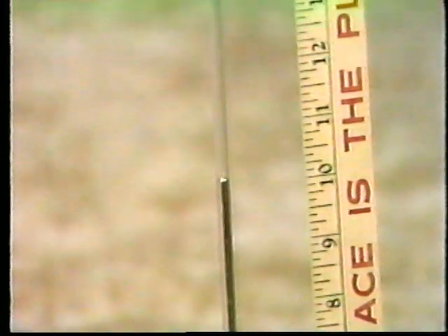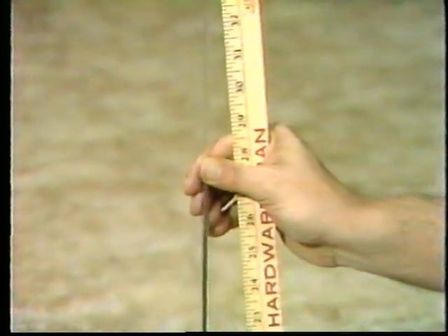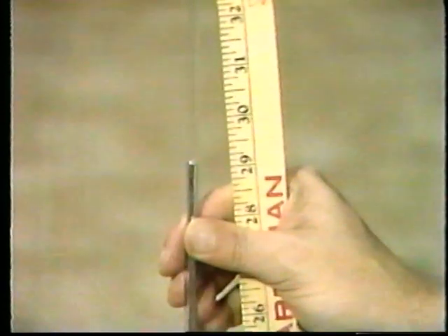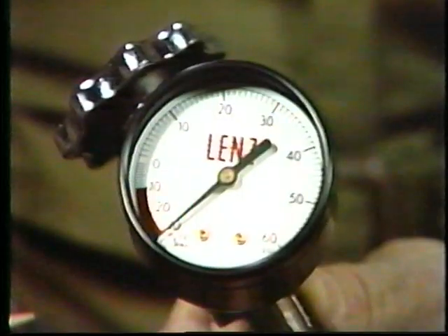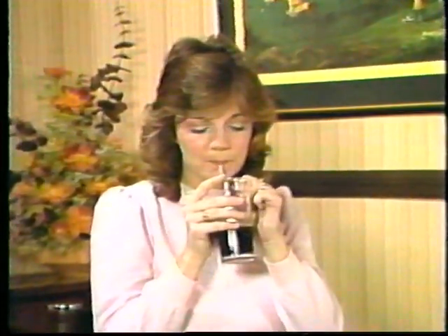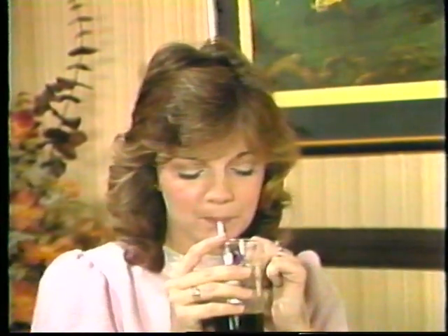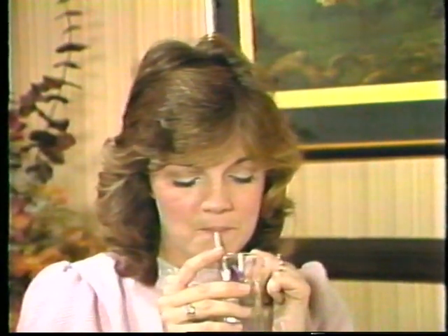If we pump all the air out of the top of the tube, then atmospheric pressure would push the mercury up approximately 30 inches. As you have noticed, we have used a vacuum gauge to measure the vacuum. Exactly the same principle is used when you drink a soft drink with a straw. You create a partial vacuum in the straw, and atmospheric pressure pushes the fluid up into your mouth.